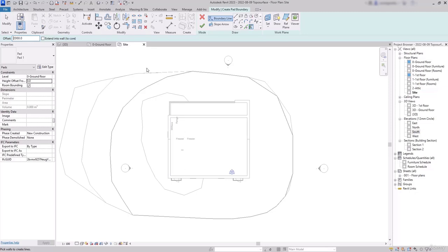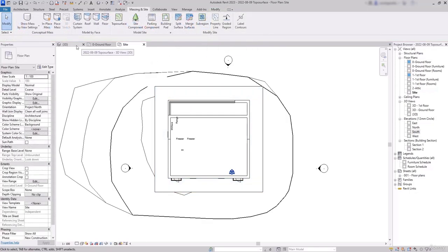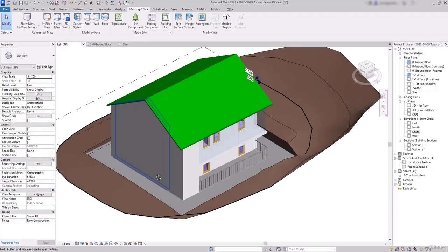which can be a bit exaggerated, but it's just for you to understand how it looks. For the drawing method, I'm going to use pick walls, and after that just click on each of them on the exterior side. Now I have to extend this line to the left, and for this remaining space, I'm going to use extend to corner and click on both lines. Now I'm going to confirm the changes, switch to the 3D view, and you can see the building pad cutting the toposurface.